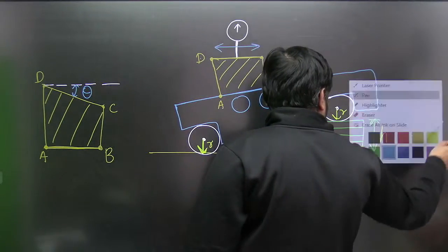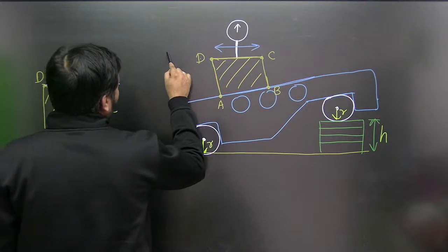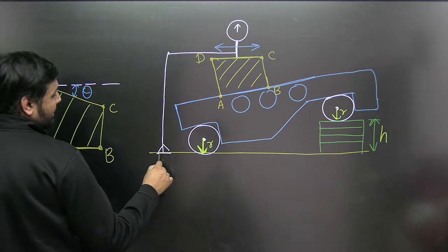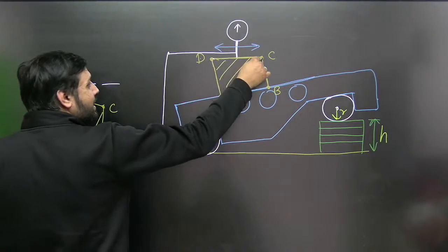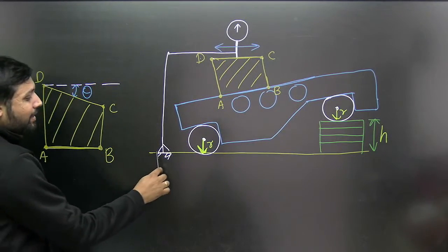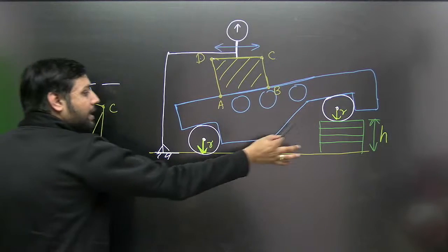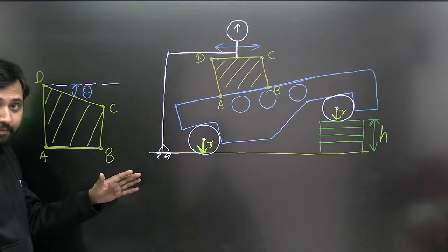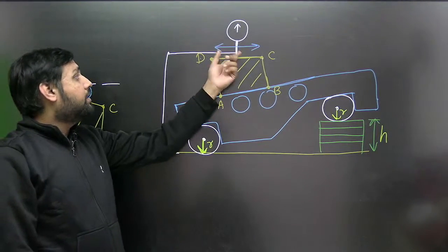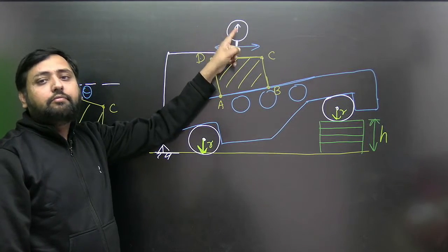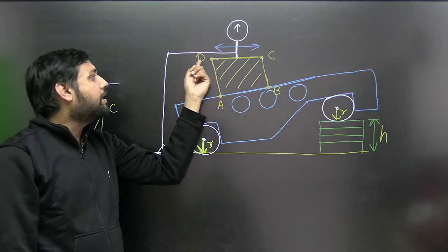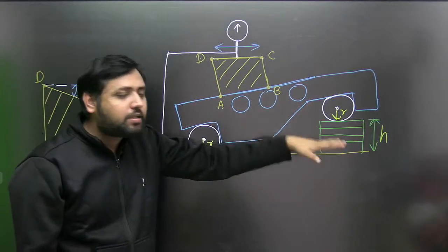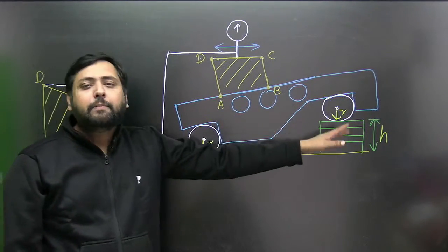My dear lovely students, if the needle is not getting deflected, then it only means that this CD surface has now gone parallel to the bottom surface on which this roller and this slip gauge are resting, isn't it? It means that the surface CD of the wedge block has become parallel to the bottom surface.